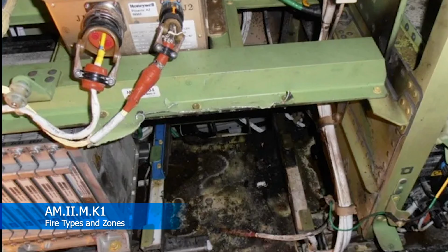If you have the right amount of oxygen and fuel available to it, it just starts doubling and doubling and bigger and bigger and bigger. Next thing you know, the whole airplane's lost. So you always want to make sure that you follow your maintenance manual inside of the E-bay particularly, and be very sensitive to any sort of FOD that's in there, anything that could potentially make it conductive and allow something to get shorted out, which could lead to an aircraft fire.